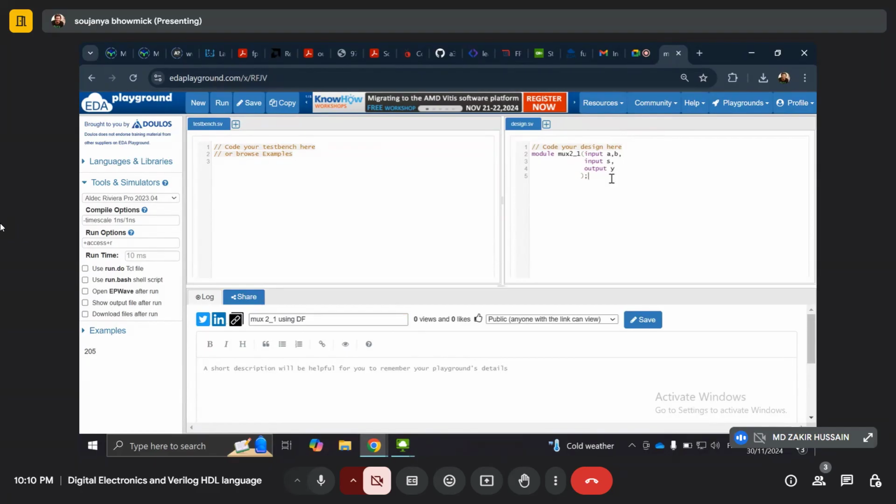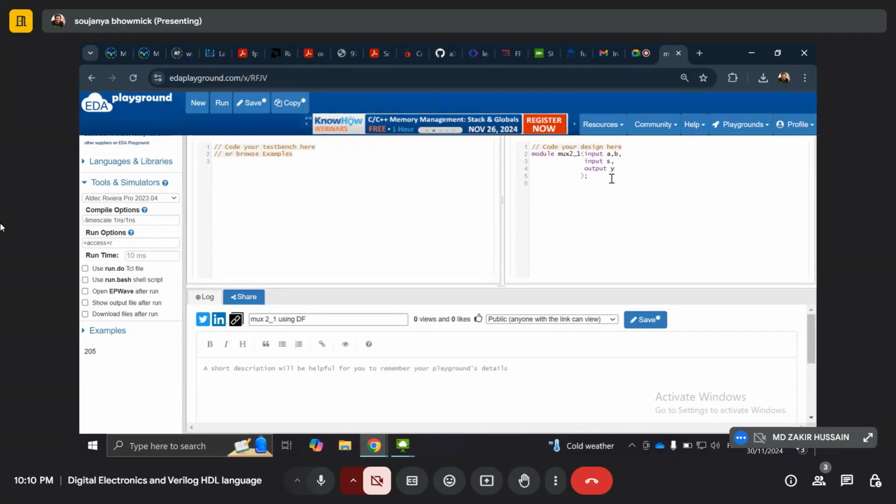There, you press enter, assign Y equal to S question mark B colon A semicolon. As in this one. Press enter. End module.